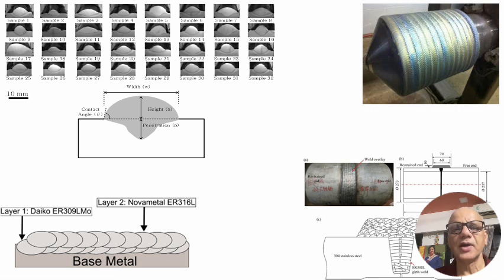See how beautifully they have done it here on the OD. On the ID also we can achieve a similar kind of a thing. Given small diameter tubes, there are mechanisms which are developed where we are able to do with the TIG welding, and 1.2 millimeter wire deposition on the internal pipe for developing a nozzle or for a passage of corrosive liquid on top of from inside it, and that's the way we'll have to really worry about it and look into it.